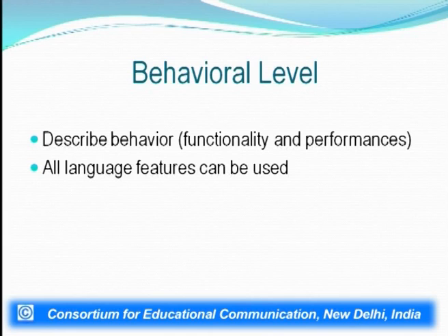Now, the behavioral level, as the name indicates, describes the behavior, that is, the functionality and performance expected out of the circuit under consideration. All language features can be used in this one, and basically we are not talking about the component level, we are talking about the behavioral level, as if for a full adder, what I am expecting is that the output sum should be given by A XOR B XOR C.